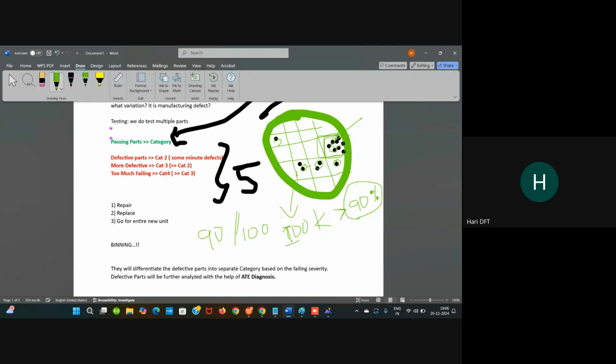Assume there are 100 dies on a single wafer. The foundry guarantees there will be a definite 90 good parts out of 100, where the other 10 will fall into the defective category. This is the success rate from TSMC. When you give a budget of 100K or something like that, it varies depending upon the quality of the silicon. Again, the overall budget for a single wafer or an entire lot will be different.